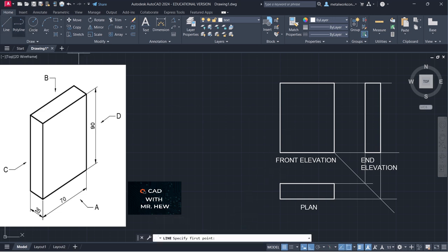All right, so we're going to go line from this point coming down. Gonna turn off ortho, which is our T-square horizontal line. We're gonna make the line 110, enter. The angle will be 225 degrees based on the AutoCAD measurement, and we didn't change it, all right?